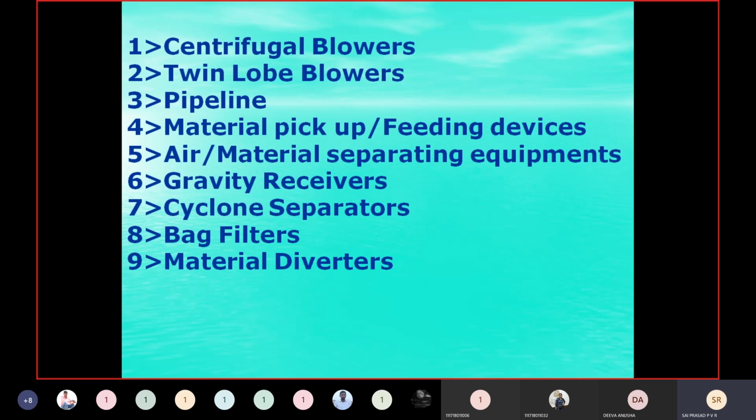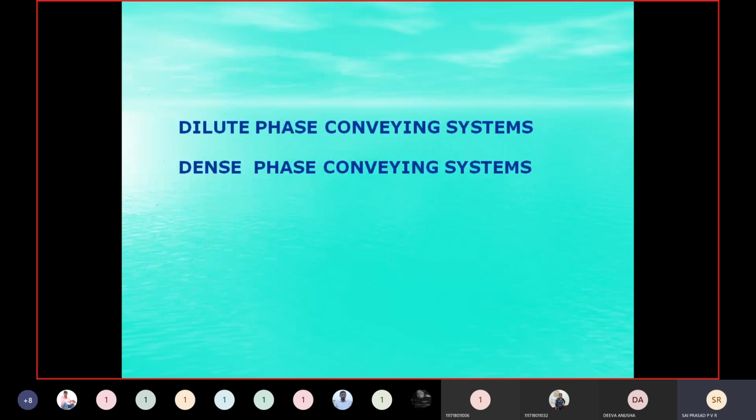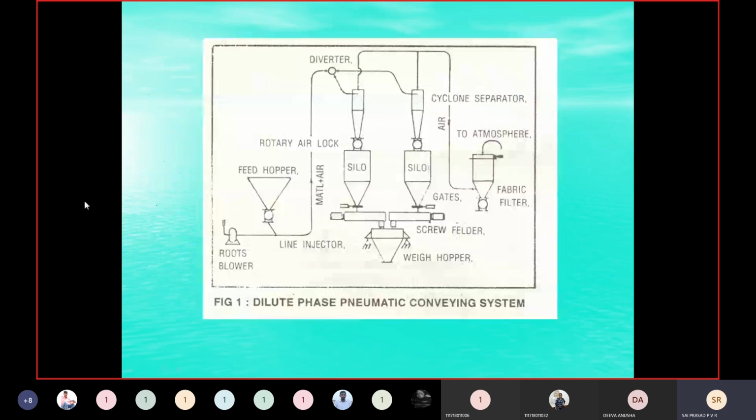So how are we going to see this in this flow sheet? We have shown a small line here, but this is actually a Venturi connector. In the Venturi, what happens when the fluid is passing in a direction in which the cross-section area is decreasing? We have studied this. The velocity increases, the pressure decreases. When the velocity increases, it can push the materials with greater energy. That's what is needed for me.